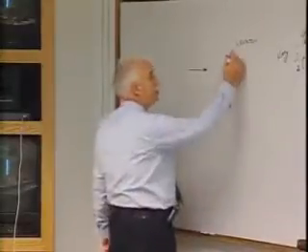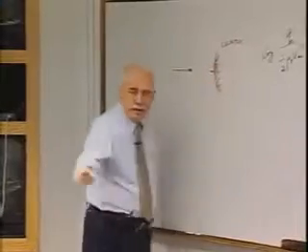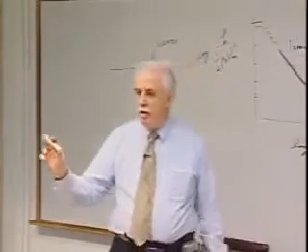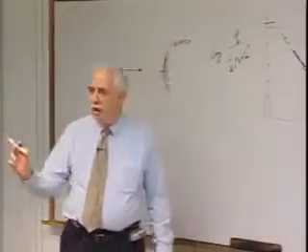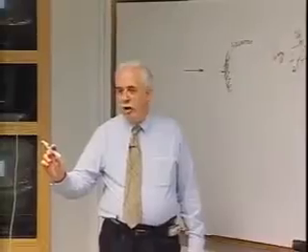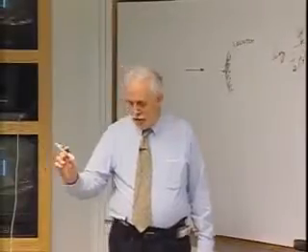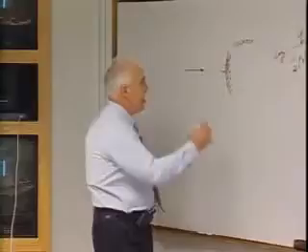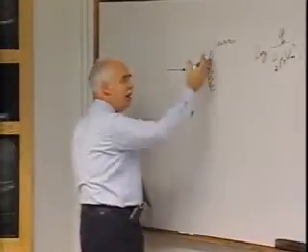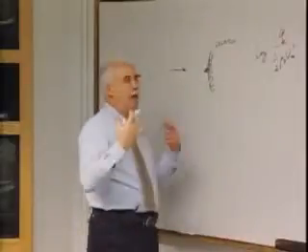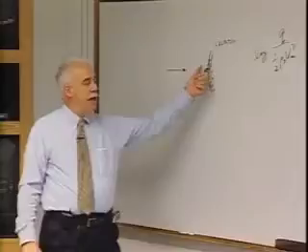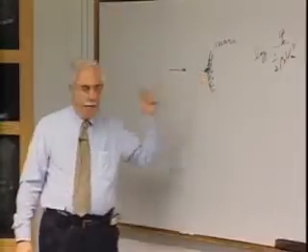So you lose some of the initial material, and that sample that Aaron passed around, that black material, was a little thicker when it started than the sample that he has, but you see what we call a char layer, where the material is decomposed. That generates a gas which at high pressures and high heating rates basically tends to absorb the energy that's coming in due to the chemical reactions primarily, and also due to the blowing.